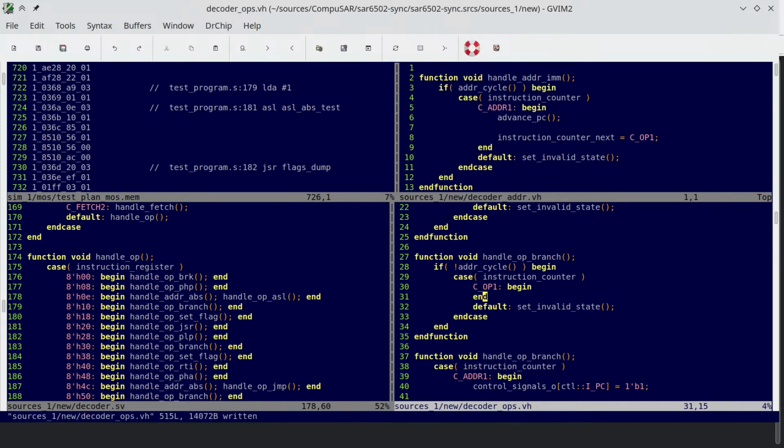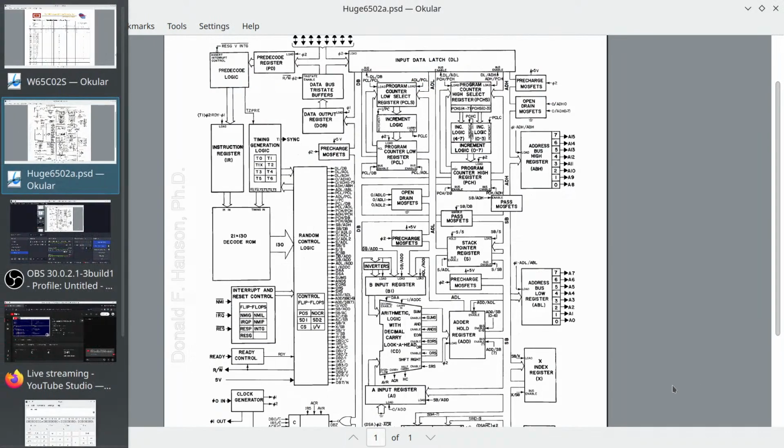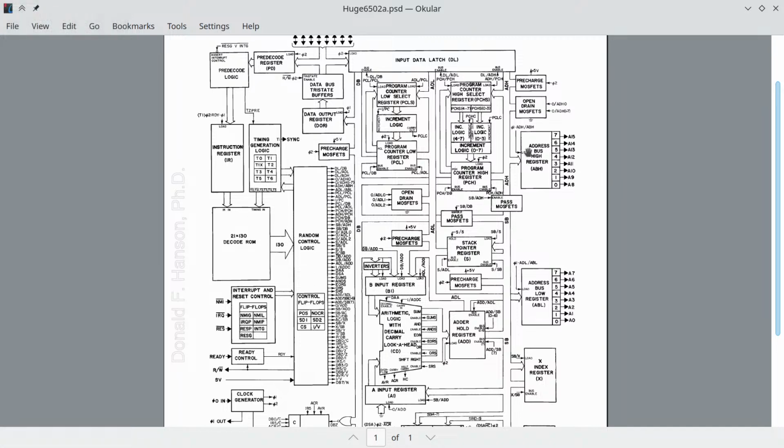And now we need to think back to the interface. The ADDR handler will call us, will switch over to the instruction cycles, if we look at the architecture, with the address bus latches holding the address that was decoded, and with the DL, the data latch, holding the data that was fetched from memory.